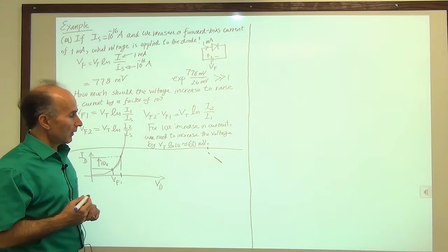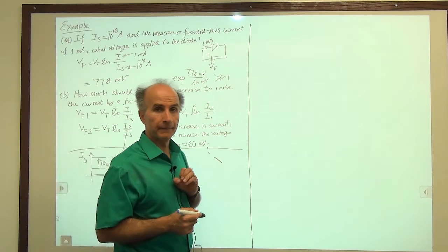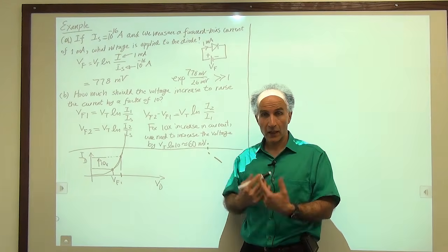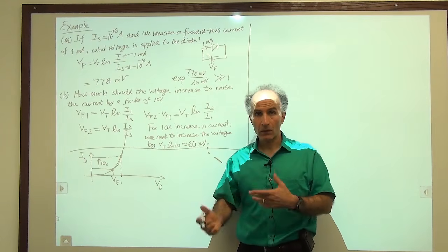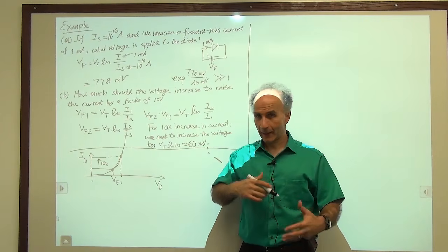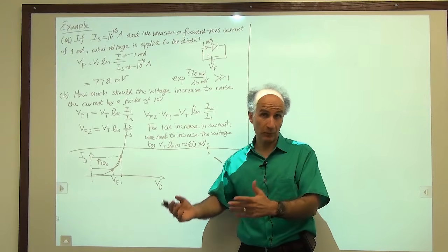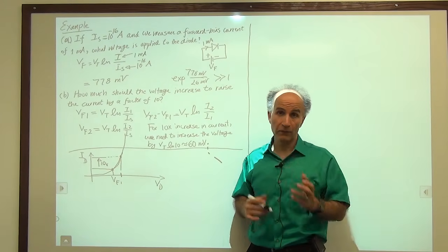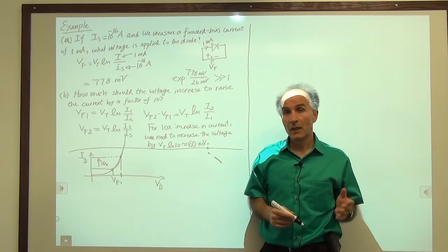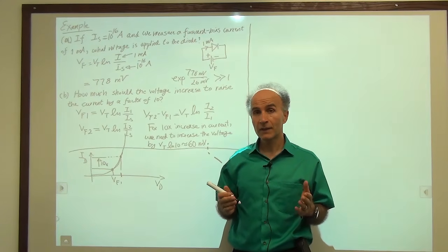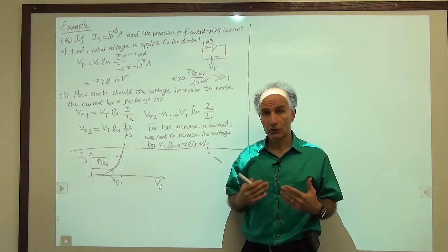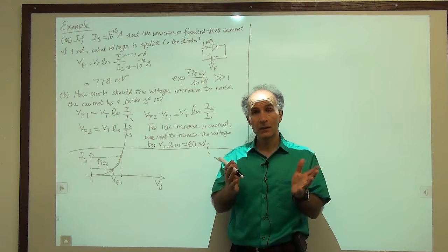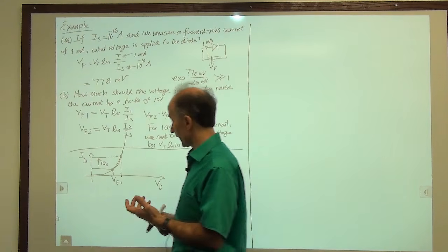Okay. All right. So this also tells us something else. If the currents that I use in practice in my field are all on the order of 1 milliamp, 2 milliamps, 3 milliamps, 4 milliamps, 5 milliamps, maybe 10 milliamps, in that range, I am not dealing with very high currents or very low currents, then I can say that the voltages that I will observe across forward bias diodes in my field are approximately what we calculated before.